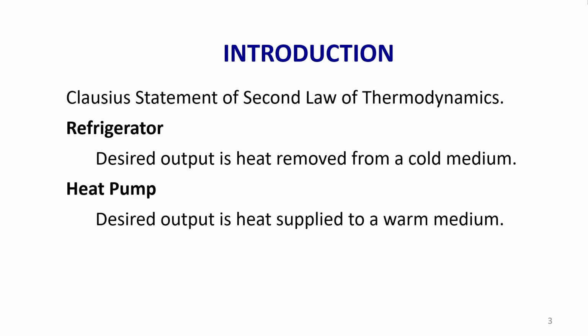So, if you recollect the second law of thermodynamics, there are two statements. One is the Kelvin-Planck statement and another one is the Clausius statement. The Kelvin-Planck statement says that for a heat engine to operate, there should be two thermal energy reservoirs. That means both source and sink should be there. An engine cannot produce net work in a thermodynamic cycle by exchanging heat with a single reservoir. So that is the Kelvin-Planck statement.